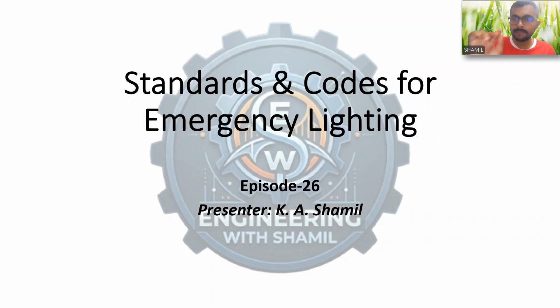But before that, let us refresh what exactly an emergency and exit light is. So an emergency and exit light is a separately dedicated circuit where, in case of a mains building failure, the emergency and exit lights will turn on automatically. The power supply will be switched from the main supply to the battery power, which is located inside the fixture, or sometimes it is centralized. If it is a centralized system, it will be a separate battery bank. So these lights turn on automatically, and they serve to illuminate the evacuation routes for the occupants to escape safely from the building during an emergency. So this is how the emergency and exit lights work.